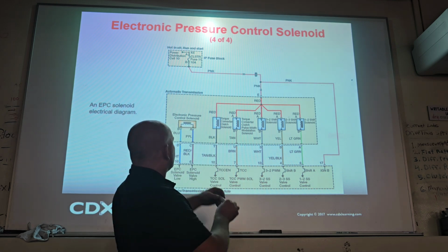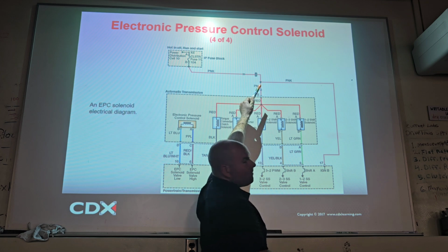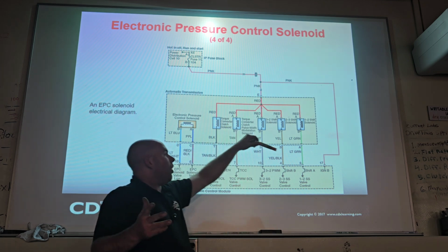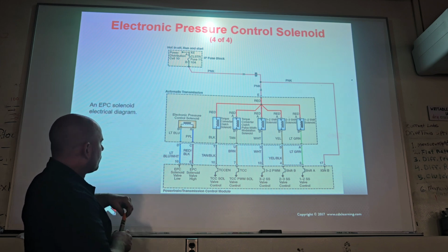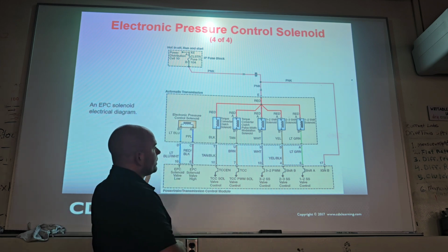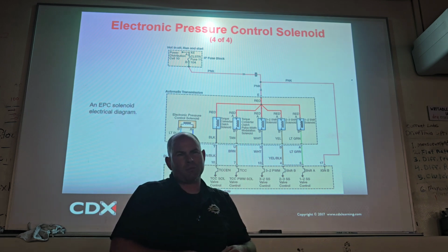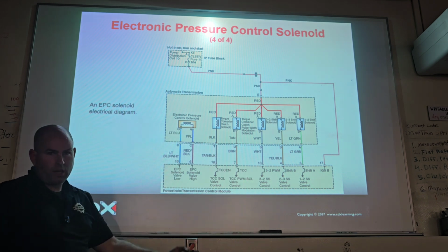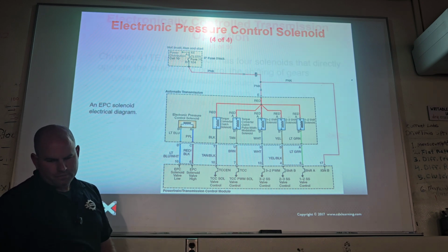The most logical would be to see, is it even getting power? Is it even powering up? So E would be first. Make sense? Or you could actually go for ground. I don't know if there's a ground here. But if it was ground for the whole transmission, you might actually consider checking ground, but it's probably going to be checking power, if you will. Cool, you got it? Not that hard.